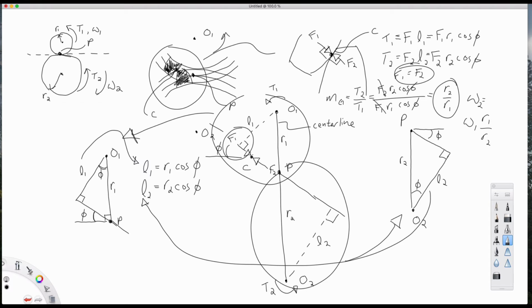So suppose we rotate some and the new contact point is right here, but the forces change and the new pressure angle is right here. Then the pitch point is right there, and R1 got smaller and R2 got larger, changing the speed ratio. In general, this is something that can happen. The speed ratio can change.